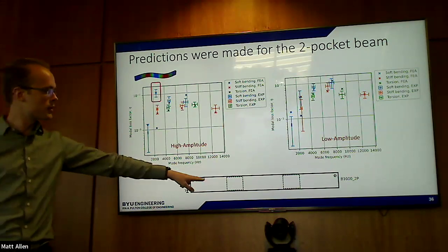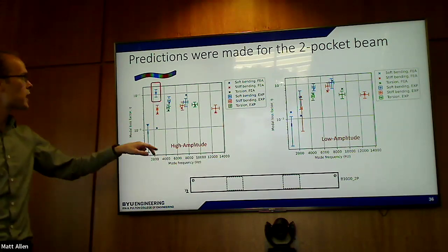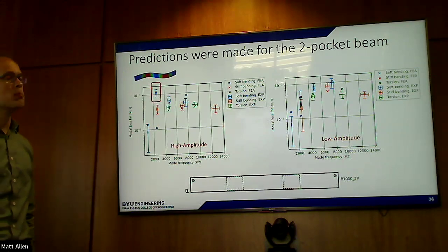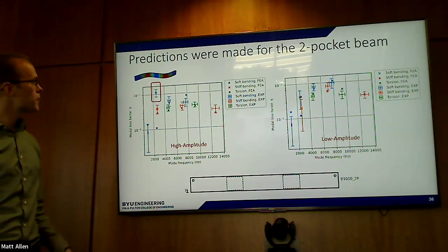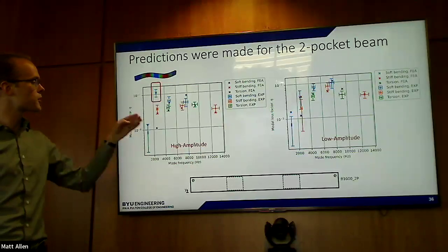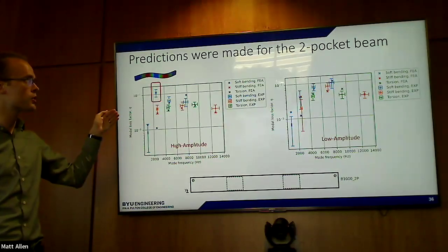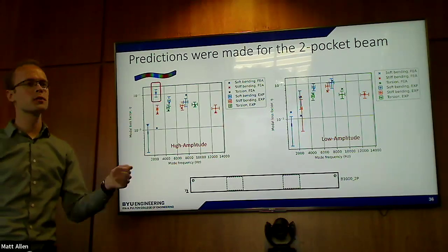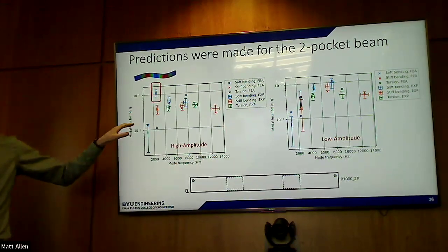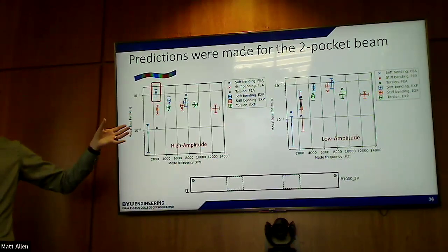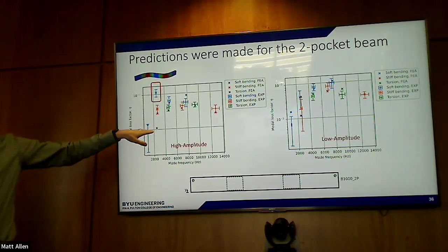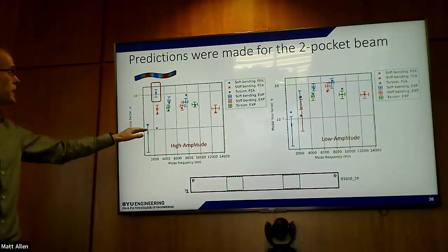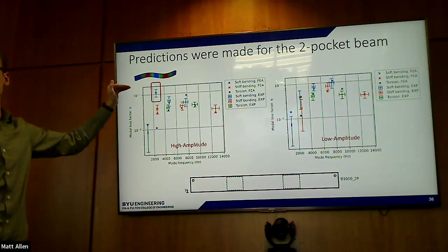This beam was designed so that these two trapped powder pockets were located exactly at these red points, which are the points that have the highest displacement in that mode. So for that mode, those powder pockets are being displaced a lot, but they're actually not being sheared almost at all. They're just being translated without being deformed. And because our model gives damping proportional to shear deformation, it predicted almost no damping due to the powder for that mode. But experimentally, especially at high amplitudes, we measured high damping.